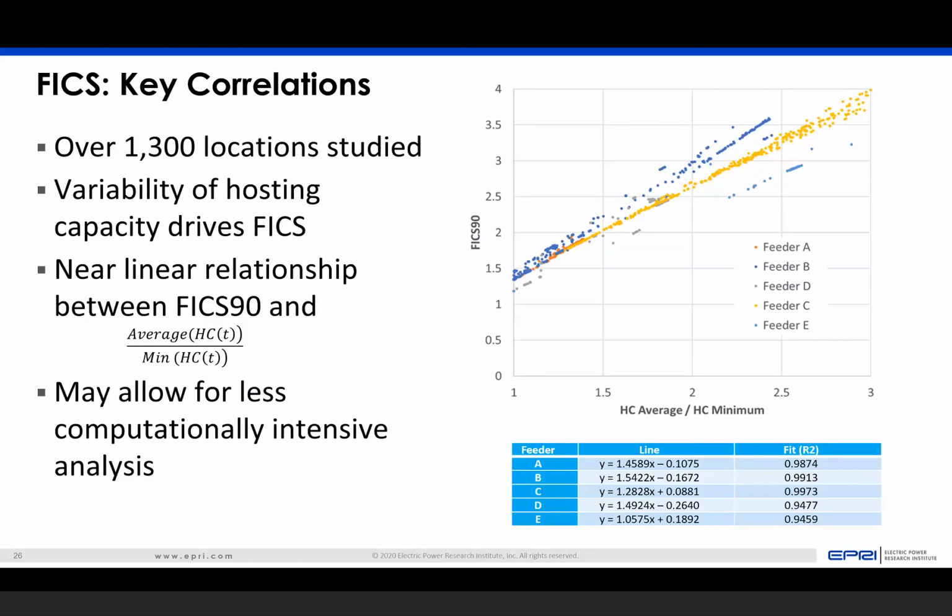As a point to note, the analysis took quite a bit of time. So for a 400 node feeder running on a single core, this could take days to run the 8760 analysis. So it's really critical to take that runtime down by applying good logic around reducing the solution space.